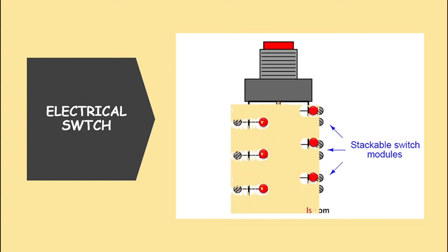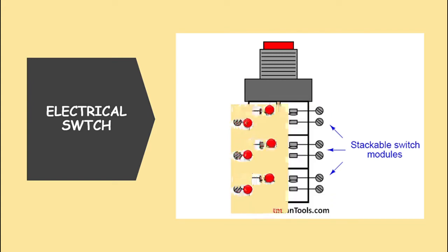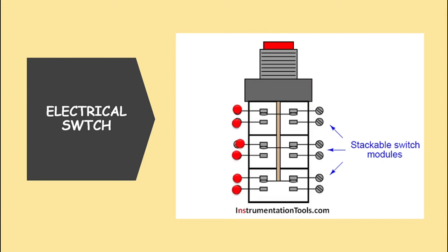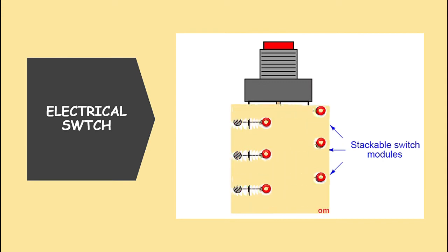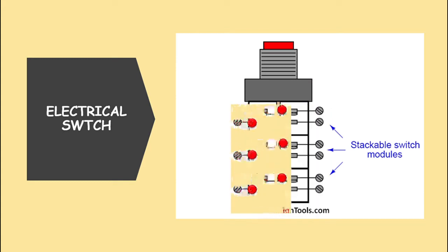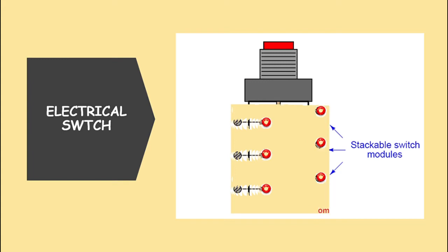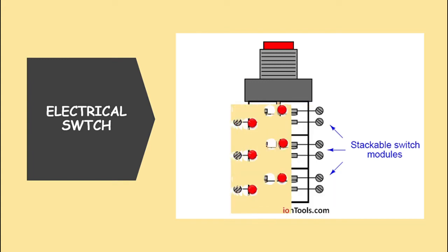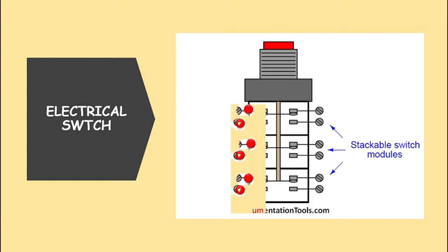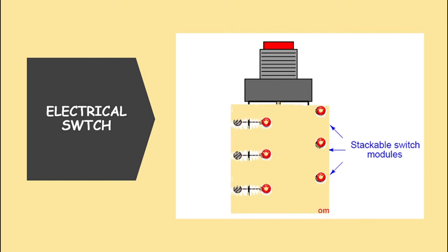Generation of an exponential decay pulse requires a switch with turn-on capability only, as the total energy stored in the capacitor bank will be discharged. Square wave pulses can be realized either by an incomplete discharge of a capacitor with a high capacitance, by a switch with on-off capability, or by a more complex pulse forming network